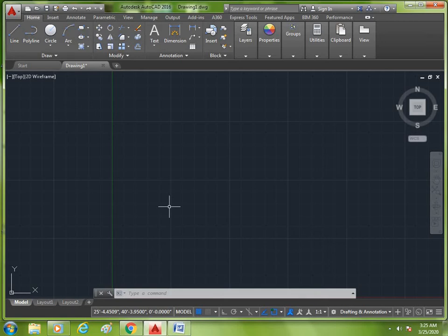The third important setting is scale factor setting. Through scale factor, you can increase or decrease the size of your object by a factor. By default, we work on standard scale, that is full scale, for more simplicity. However, if your drawing is large or you are working on an extremely small object, you can increase or decrease your object by a factor.